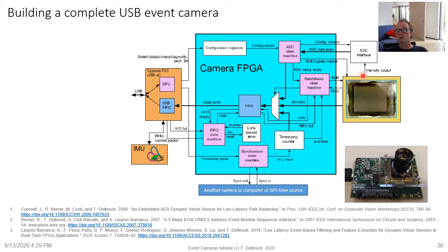on your Davis chip, you have an address event interface, and in the case of our chip, it's an asynchronous interface. So it uses a 4-phase handshake with this word serial protocol that I just showed previously. When the chip has an event to send, it raises request. The handshake state machine then raises acknowledge. We read the address from the chip, then the Davis chip lowers request and the handshake machine lowers acknowledge. That's why it's called 4-phase, right?